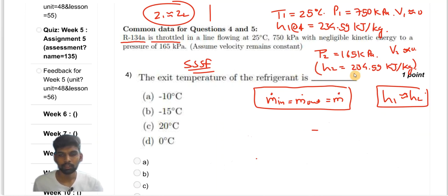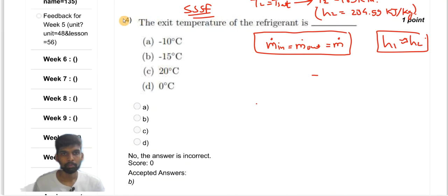So at state 1 we have got the enthalpy from this property. At state 2, pressure is known to us and enthalpy is known to us. When we look at the table at this pressure, we will find that this enthalpy value lies between the saturated liquid and saturated vapor state. So we are in the wet vapor region, so T2 will be T sat, the saturation temperature at this pressure, and its value is equal to...